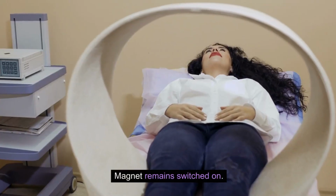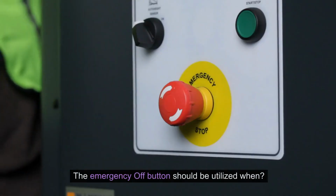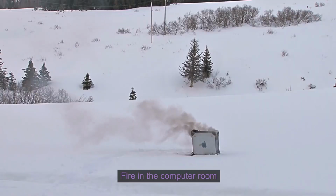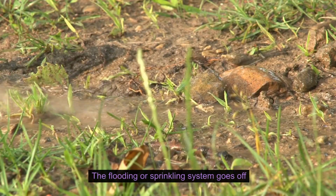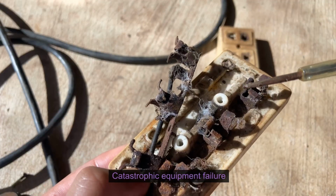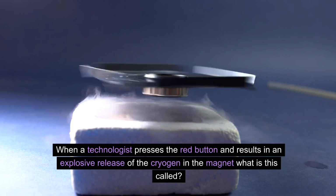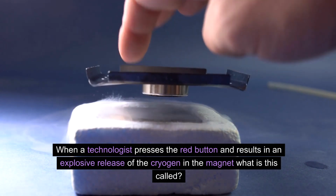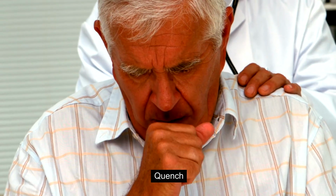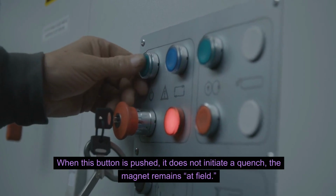The emergency stop button turns off all electrical power to the magnet's power distribution unit, PDU. The magnet remains switched on. Shutting down the power to the PDU is required for life-threatening situations. Question: the emergency off button should be utilized when? Fire in the computer room, sparks and loud noises from the scan room, the flooding or sprinkling system goes off, or catastrophic equipment failure. Question: when a technologist presses the red button and results in an explosive release of the cryogen in the magnet, what is this called? Answer: quench. When this button is pushed, it does not initiate a quench. The magnet remains at field.